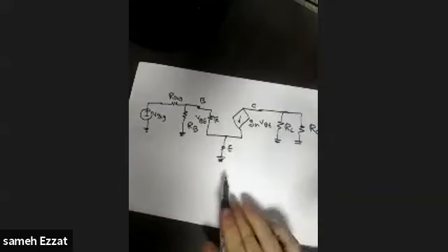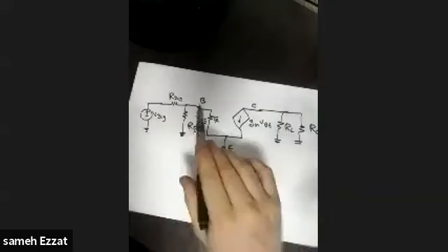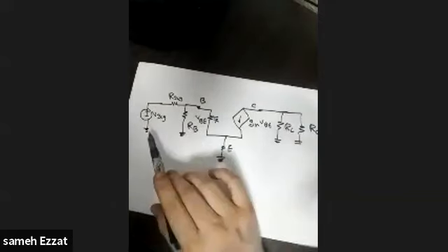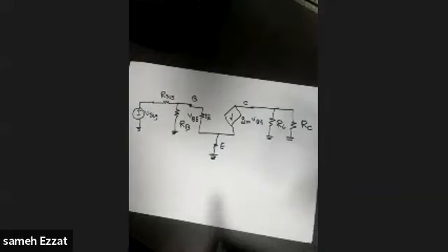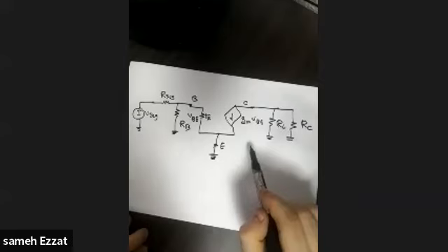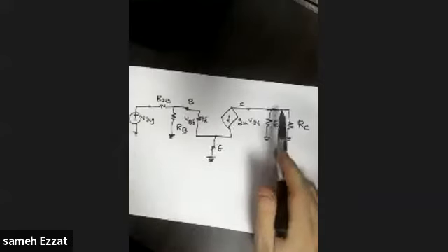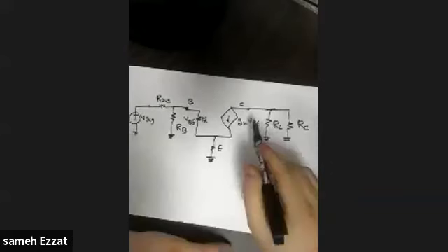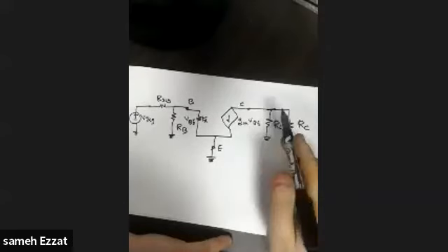So this is our circuit now. We have the emitter to the ground. We have the base to R capital B and R swing and V swing, and we have the collector connected here. Please remember that sometimes you may have an output resistance here, which, if you remember, indicates the output resistance of the MOSFET in the active region, where you have this tilting or slope effect, if you remember from the MOSFET and the BJT. So sometimes you may have an output resistance here, which will not actually make a difference in the solution. Okay, so this is the configuration.